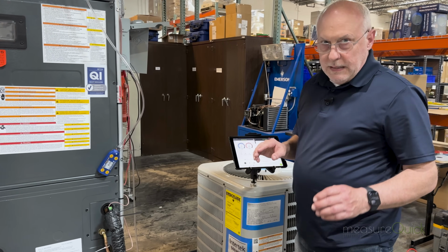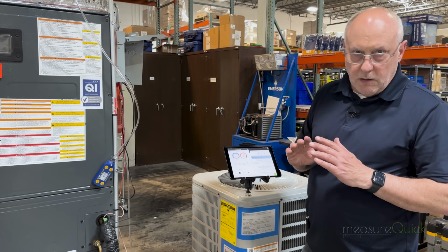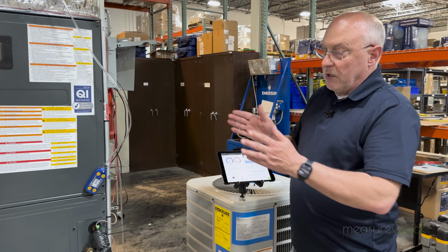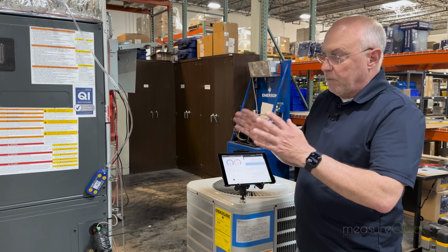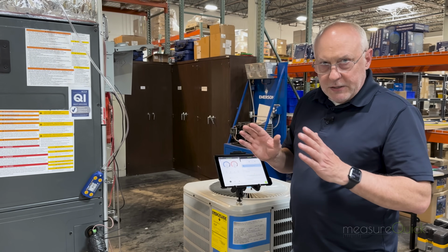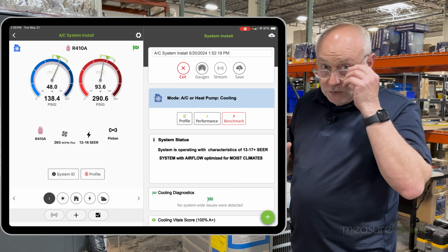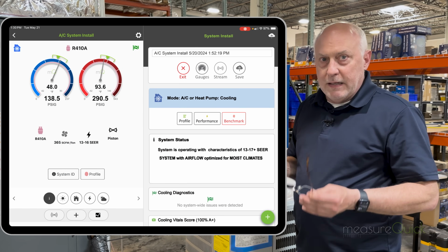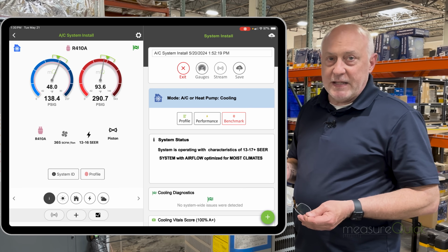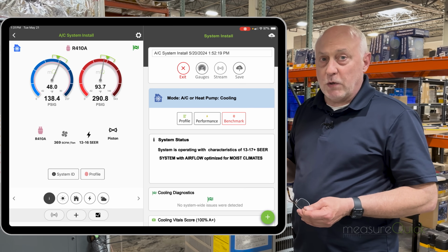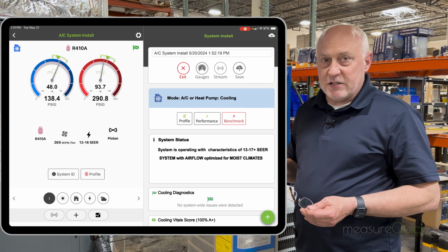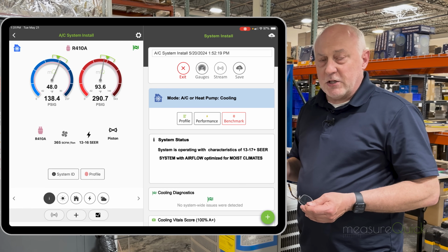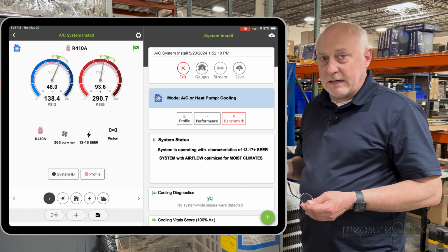All right, so now that we've got everything all set up, we got the condenser coil cleaned, we've checked the filter, we've made sure our static pressure's in range, our coil's clean, our blower's clean. Now we're okay to check charge. It's very important that you don't skip that step. A lot of people want to go immediately hook up gauges on a system before they make sure everything is clean and the airflow is correct, and that's where you really make the biggest mistakes in our industry. So those preliminary steps are very, very critical to making sure that the system's actually going to operate correctly.